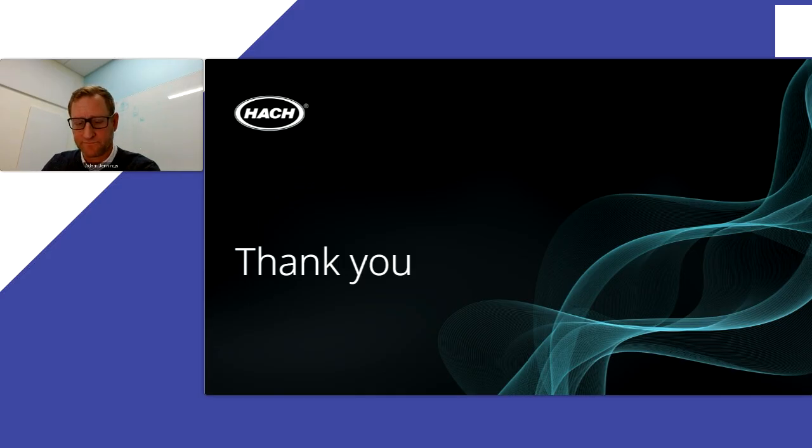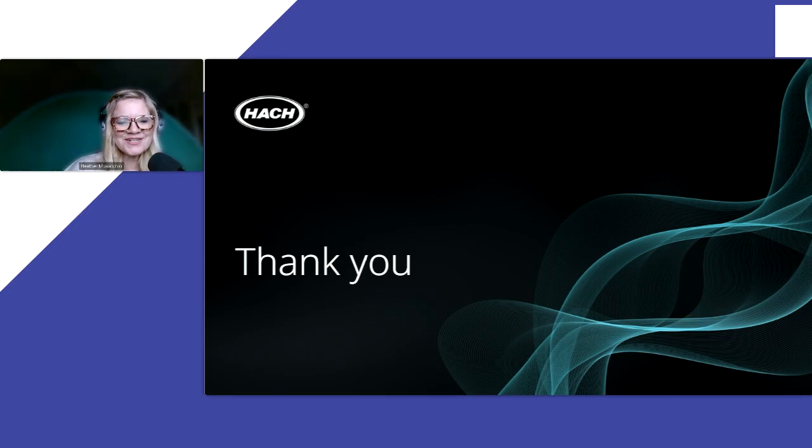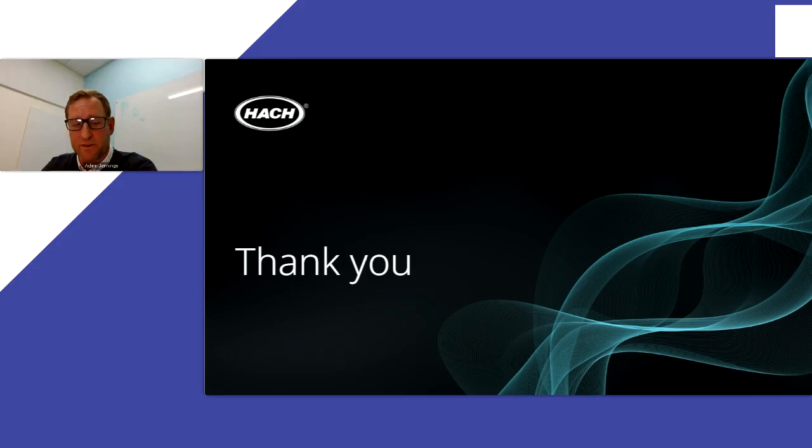Okay, excellent. Thank you very much. Moving on, another audience member would like to know, are ammonia polishing technologies a viable option for achieving stringent ammonia limits in the effluent? Can you help with that? Sure. When you have high levels of ammonia in a side stream, for example, coming from a centrate, maybe a centrate treatment or belt filter press, that sort of thing, if you can remove some of that ammonia in a side stream deammonification basin, so that you're not having to treat that in the mainstream, that's absolutely a viable option.